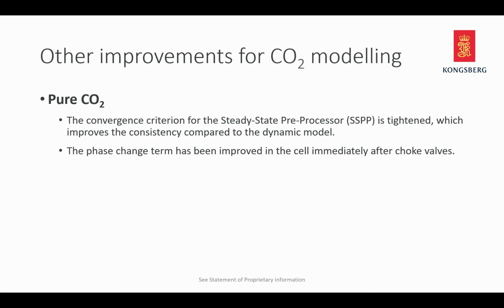I'd like to mention a couple of improvements we have implemented for pure CO2. The consistency between the steady-state preprocessor and the dynamic model has been improved after we tightened the convergence criterion for the steady-state preprocessor. The phase change has also been improved in the cell immediately after the choke valve.